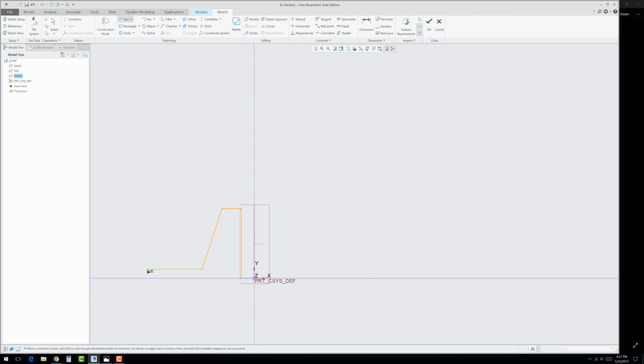Stay away from any little equal symbols. What I mean by that, watch this. If I go across here, eventually I get a little equal symbol to the right of my pointer along with the horizontal. You don't want that. Stay away from that one. So drag it back so you don't accidentally get that. Equal symbols can be useful. They could be turned off too, but it is something that we just don't want right yet.